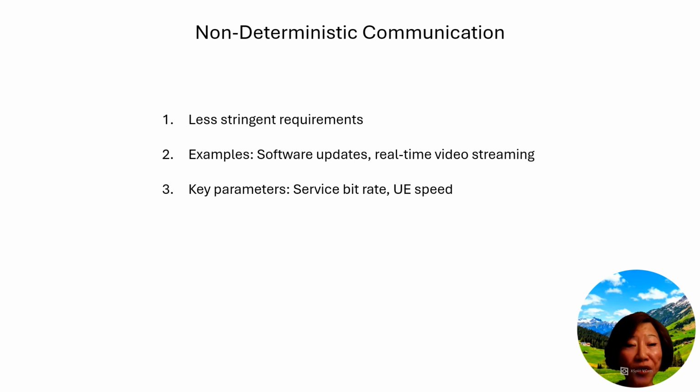Supporting high UE mobility is a key feature of 5G, achieved through advanced beam management techniques and rapid handover procedures. In factory settings, this might involve dense networks of small cells to provide continuous coverage, with techniques like coordinated multipoint (CoMP) transmission to smoothly hand over connections between cells. The system also employs sophisticated channel estimation and prediction algorithms to maintain link quality even at high speeds.